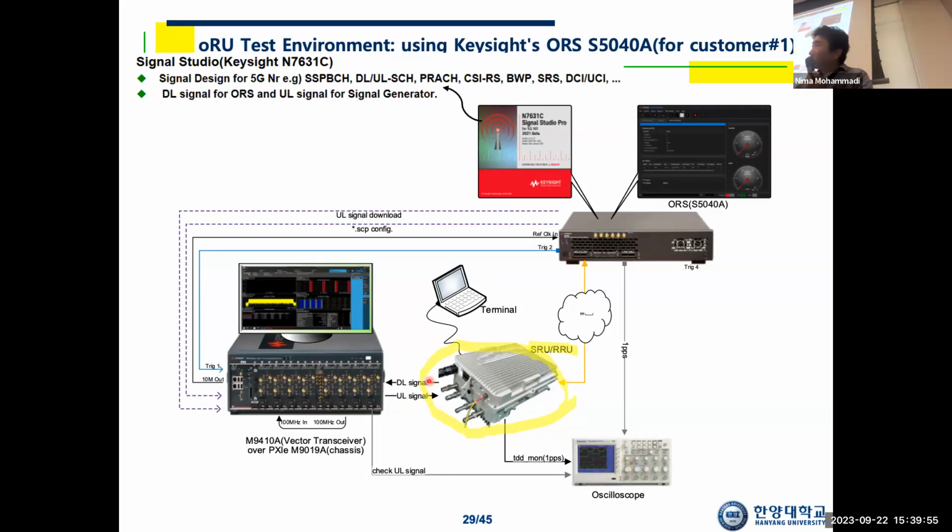Now, if this procedure can be successfully done, then you are proved okay with the downlink signal, because what you have processed is the downlink packet which includes all the requirements of your customers. If anything goes wrong, even if there's no problem with that procedure, then the reason is one of these two. Your radio unit has a problem with the uplink signal, or your ODU is wrong.